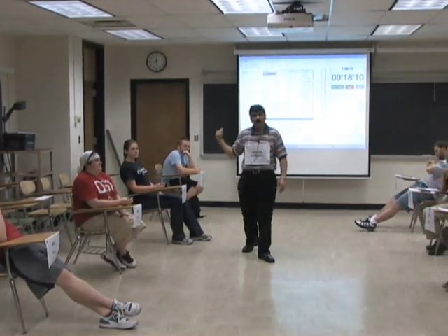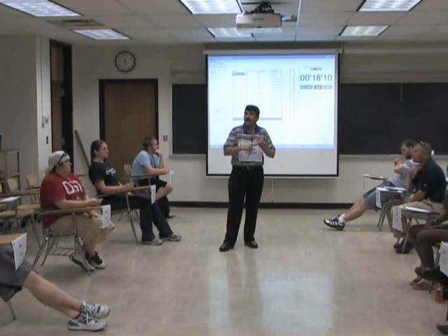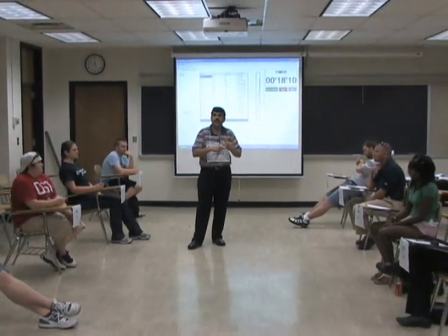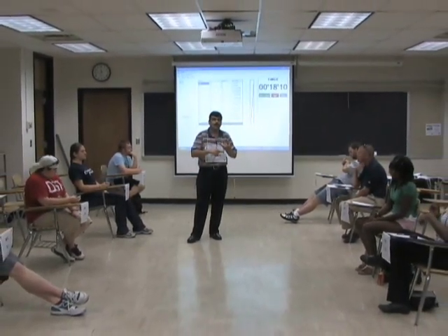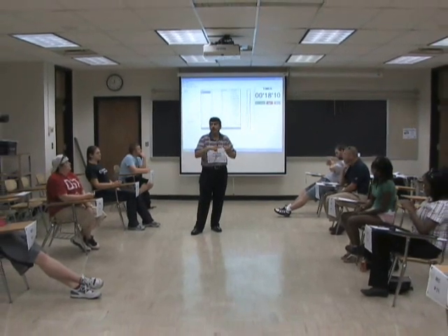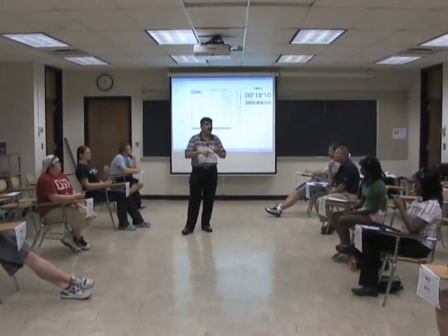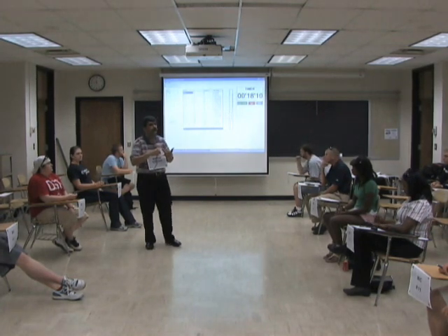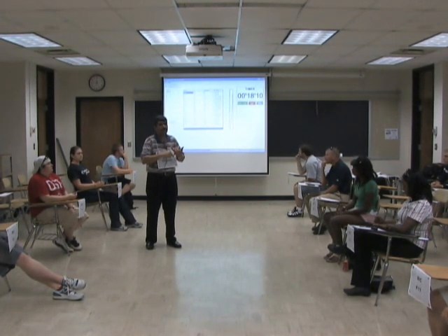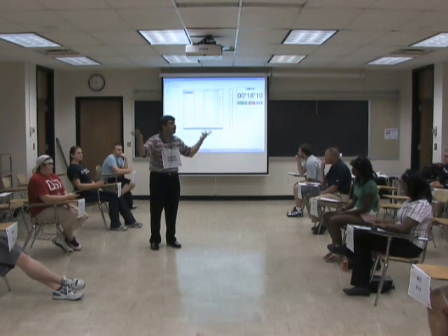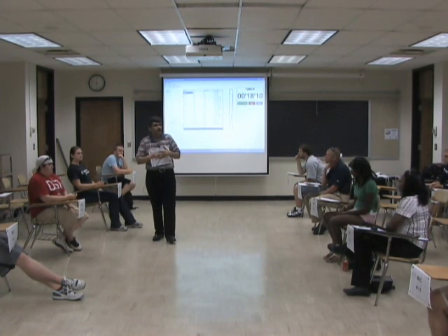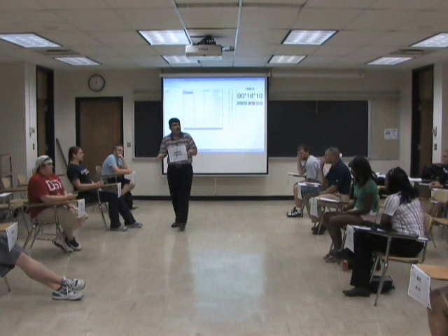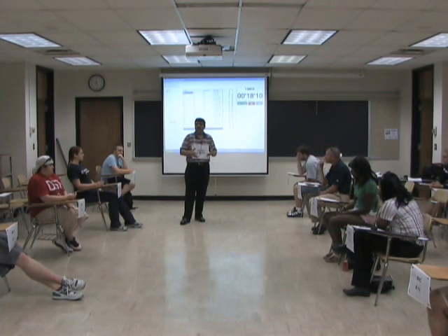A cell is where you put together a lot of equipment and you finish a family of products. Another important thing was, I started the system empty. You wouldn't do that. The previous shift should have put at least one job in queue at each machine as per the schedule, so that when the operators come in the next shift, they already have work in queue, and are not running around the place saying, hey, where's my first job? When can I start my first job? So the idea of the process layout badly done is it naturally encourages very wasteful work.